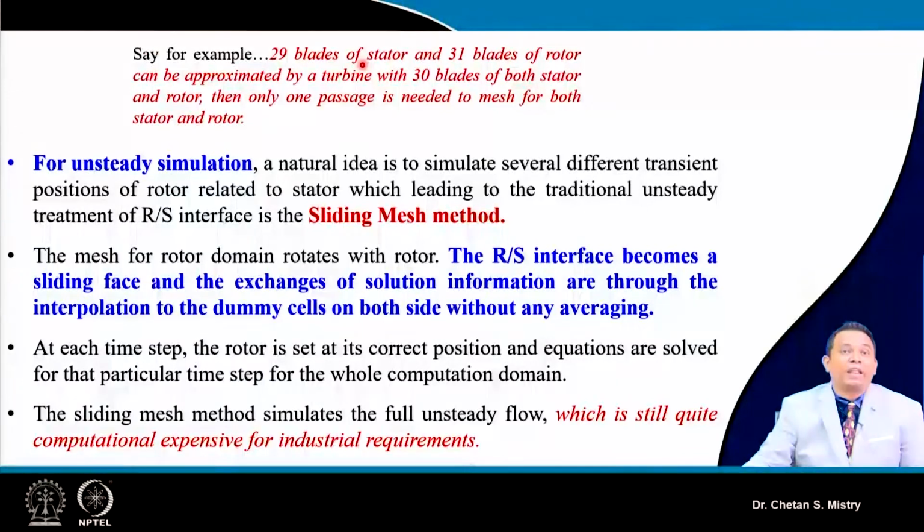Now the next approach is unsteady simulation. For this unsteady simulation, mainly we are looking at the exchange of data between rotor and stator, which happens with the sliding mesh approach. Under that configuration, whatever data we analyze at the exit of the rotor domain, using dummy cells, it does all the calculation. That data is transferred to the next stator blade, and this helps us understand the detailed flow field.